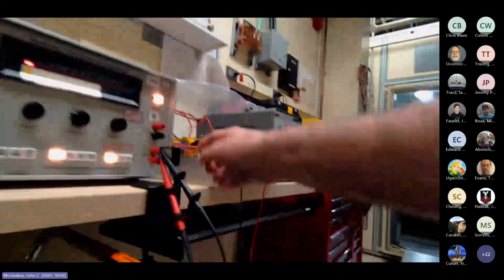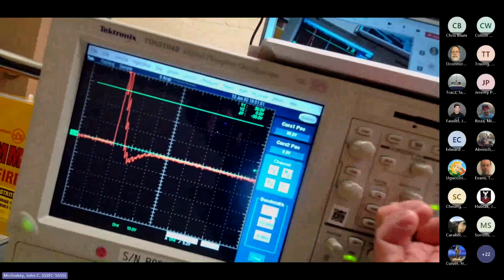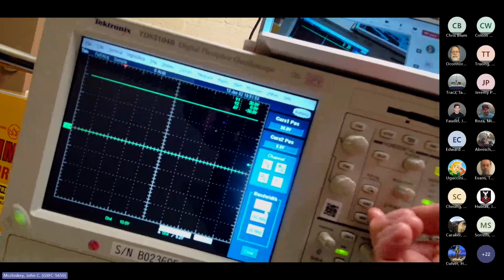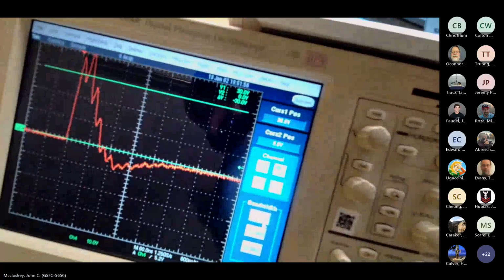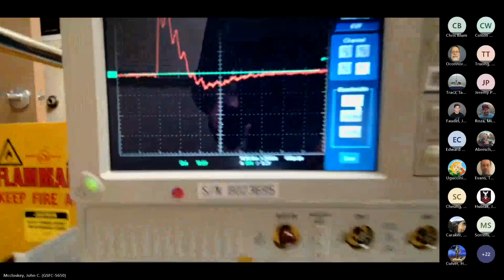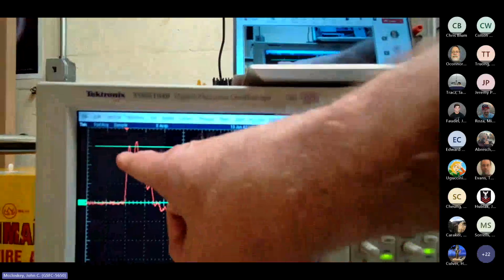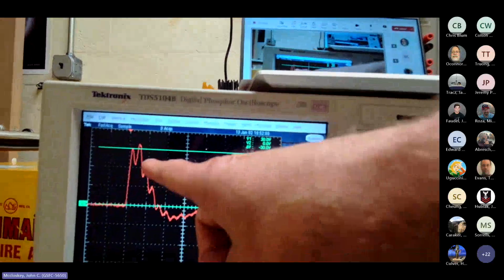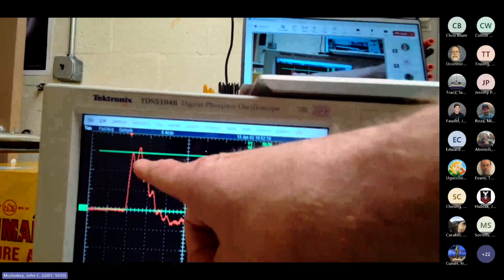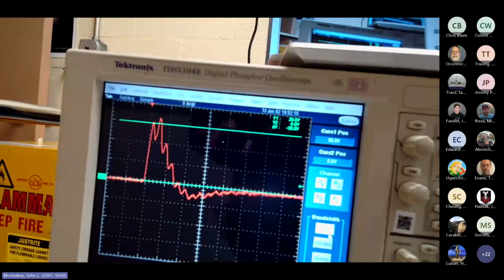I would be inclined to start with the resistor module, so that now you're getting the best behaved version of the signal that you can get. Let's take this down. And so with that ringing, you make a judgment call as to what you are going to set the amplitude at. I would be inclined here, with that second peak being a little bit higher, to set my 30 volts to that first peak. I'm going to set that at the 30 volt line.